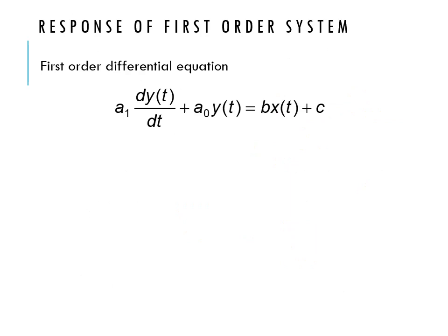Now we try to solve the differential equation that represents the dynamics of the process and their control system. The objective is to find how the output signal responds to the input forcing function. We assume that initial conditions are at steady state, where the time derivative is 0, and define all variables as deviations from their initial value. This forces the initial value of the deviation variable also to be 0.